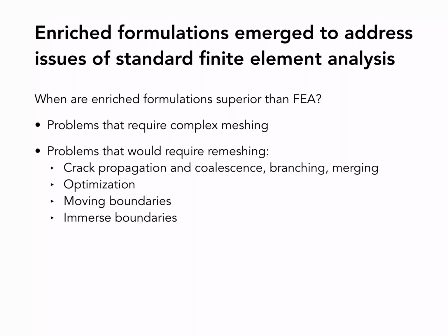Moving boundaries, immersed boundaries. Who has an idea what an immersed boundary is? No one. Okay, imagine you want to model this marker. I don't want to create a mesh that actually follows the boundary of the marker, but I just include this marker inside a box. That's my finite element mesh. It's just a very simple structured box of finite elements. I'm immersing my marker geometry in that. You can actually obtain a solution, and we're doing a super nice job in that direction too.